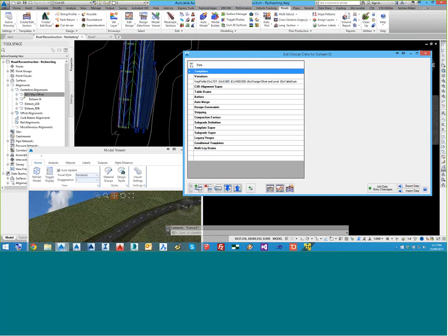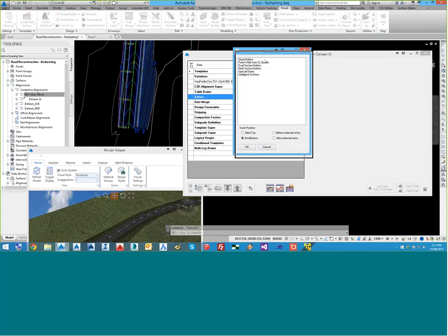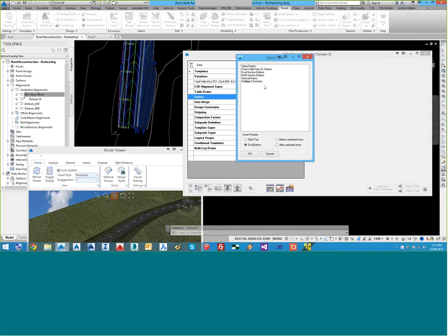So to override a batter, I select on the batter's entry and hit the button with the green plus to add one in. You'll see the list of different types of batters in here. Some of these have been in the software for quite a while. Some of them are even, I suppose, obsolete. The multi-section batters routine has been replaced with the intelligent sections command.